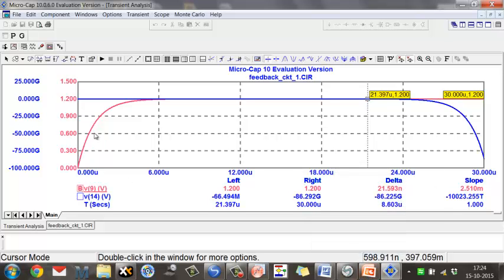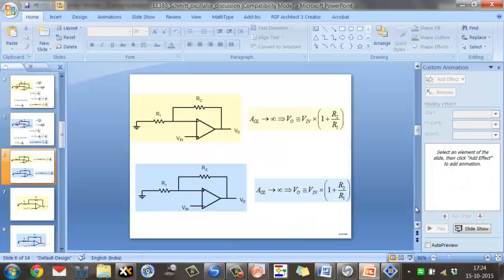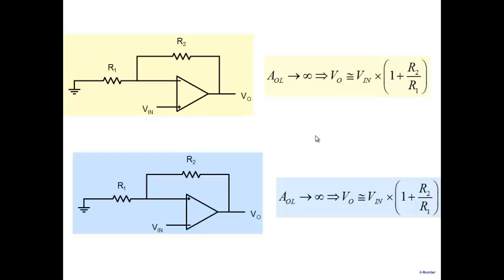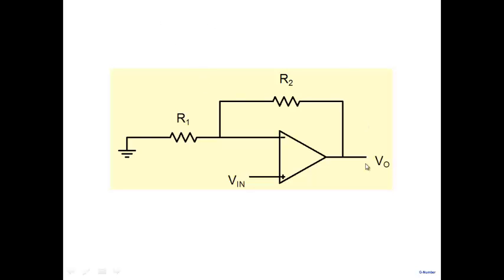And once you do that, you see that with positive feedback the output is being driven towards a very high value, and the negative feedback, of course, goes to the required state. You can see it from here too. If I have a negative feedback system, let's say initially this is 0, and suddenly I apply 0.1, what happens? I develop a voltage of 0.1 between these two nodes. And then after a delay, as it goes through the op amp, what will it try to do? Force it up. This voltage will try to increase.